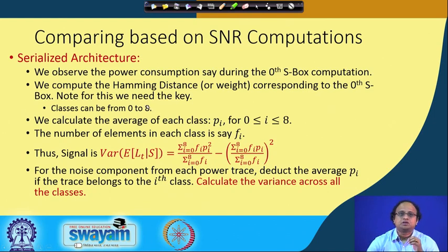If you know the key, then, say you are working from the ciphertext, you can find out the target register you are talking about, and the corresponding Hamming weight or Hamming distance for that state. That would imply that if you take many power observations, you can split them into bins depending upon their Hamming class.